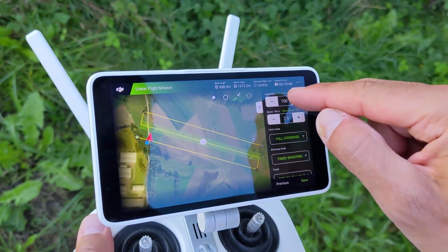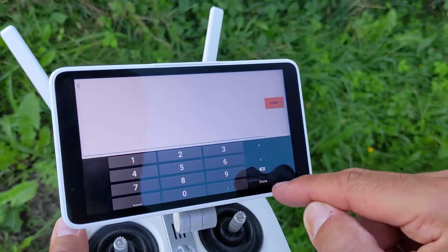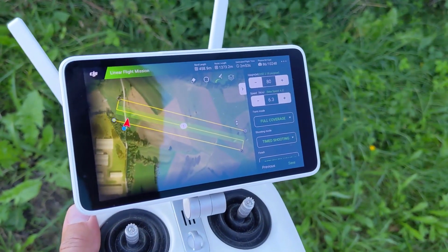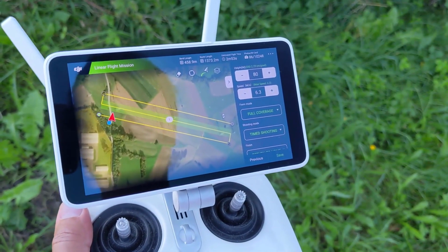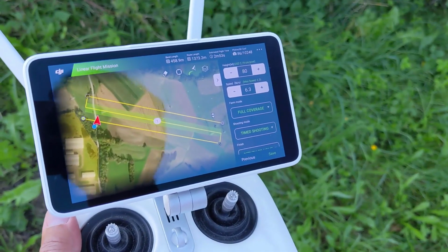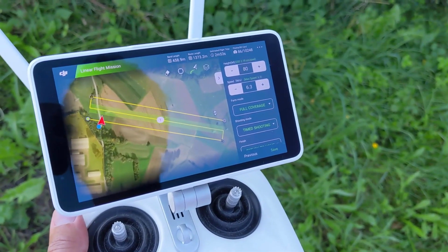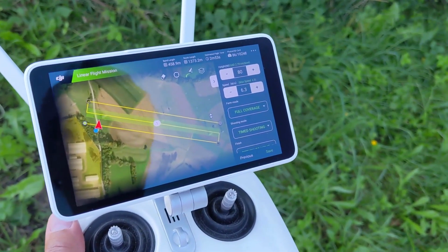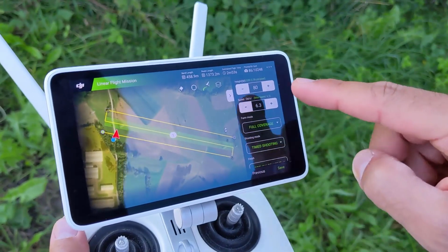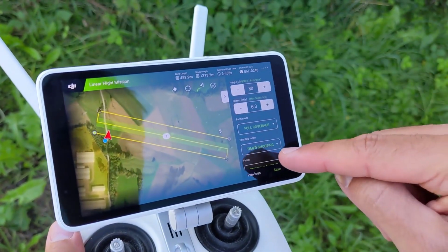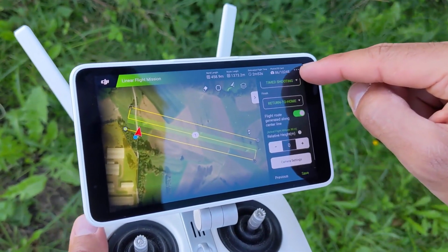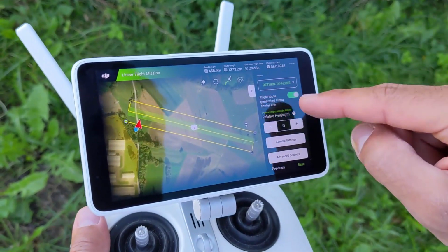Okay, I will set here 80-meter flying height, because I need to have high resolution also on the power line cables. The dimension of these power lines is probably 2 or 3 centimeters wide, and we need to see them on the image accurately. So the flying height is the first one. I changed it to 80. Then everything else is okay here.